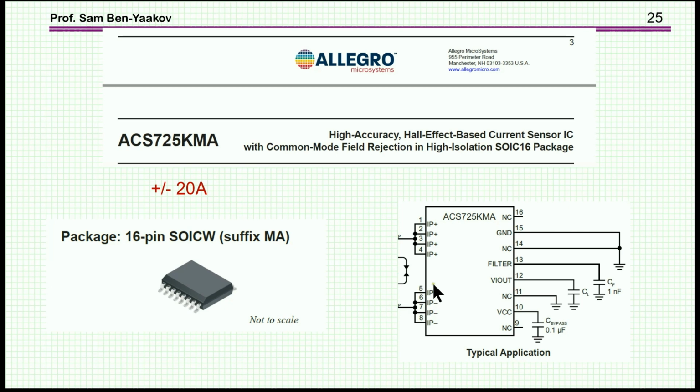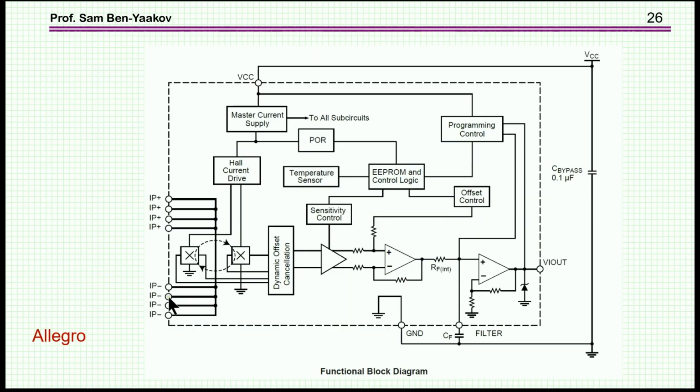Now, this element does not have a magnetic core, but it does have two Hall effect elements put, as I understand, on the both sides of the wire that is passing through the device. And the idea here is that an external magnetic field that will come here will affect these two the same thing, and they'll sort of cancel each other, while the effective or the signal you want to measure is in opposite directions, so that you add the useful signal and you subtract the interference.